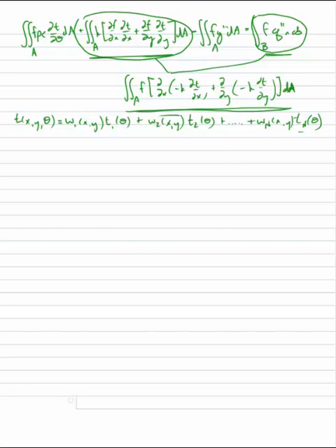And what we're going to find is that each of these temperatures, T1, T2 through Tn, are going to be the temperatures at nodes. So we'll have a bunch of these nodes in our finite element mesh. So if this is node I, T sub I, which is only a function of time, would be the temperature at this node right here.